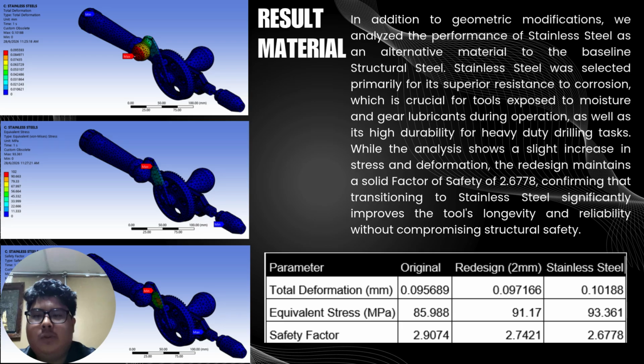As the table shows, while there is a slight trade off in deformation compared to the 2 mm redesign, we still achieve a very solid factor of safety of 2.67. This demonstrates that moving to the stainless steel is a valuable part to significantly improve the tool longevity.